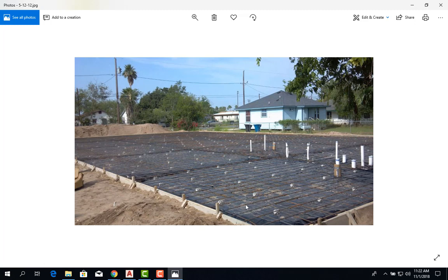Okay, so this is the rebar that the engineer decided that we needed, and I think he went a little bit on the safe side. When I spoke to the guy that did our foundation, he has a lot of experience. He was telling me the engineer put I think it was number 6 or number 7 rebar, I forgot which. And he said usually you can go with a thinner one, and it'll hold. He has the experience in the field. He says, you want to save some money? Go ahead. We can put rebar that's not as heavy as this one.